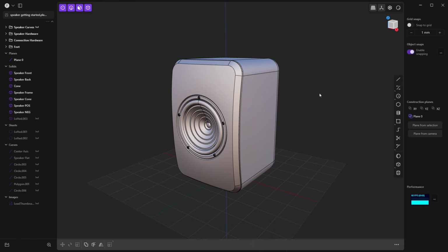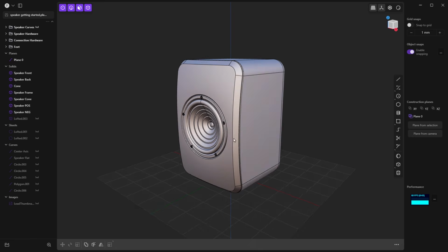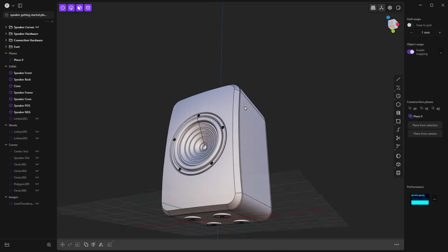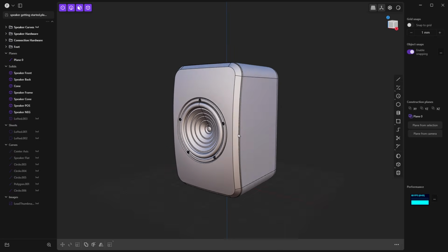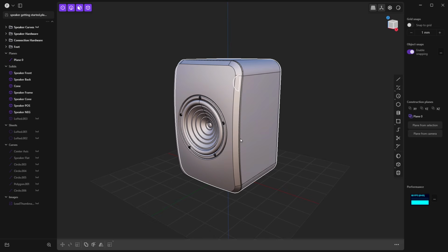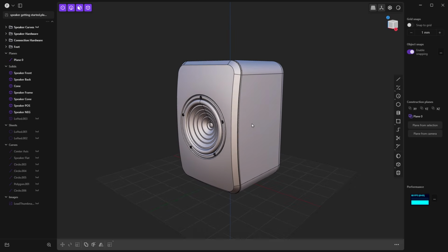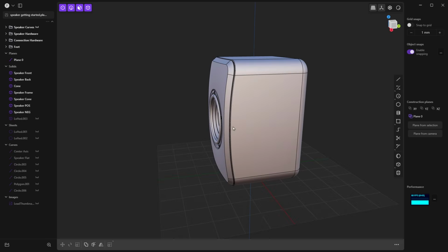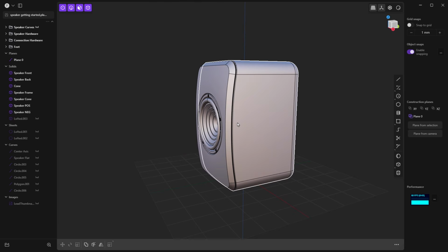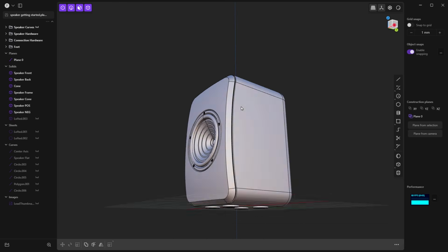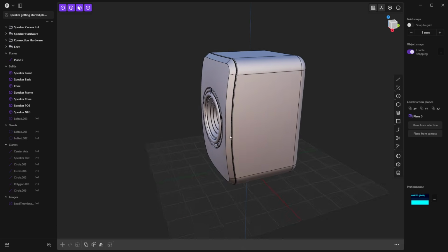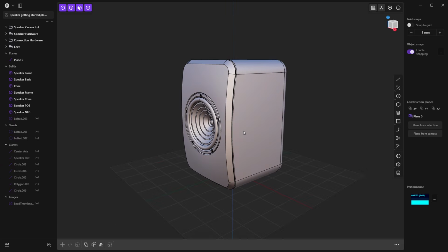Once you have looked at those settings, then spend some time playing around, understanding how you can move your objects around. If you're using the default Plasticity setting, you're going to hold down the middle mouse button. If you have a traditional style mouse, then you're going to push down the mouse wheel. If you have a CAD mouse where you've got 3 buttons, then you'll have an actual third button. But for the most part, you'll push that down and that'll allow you to orbit your object.